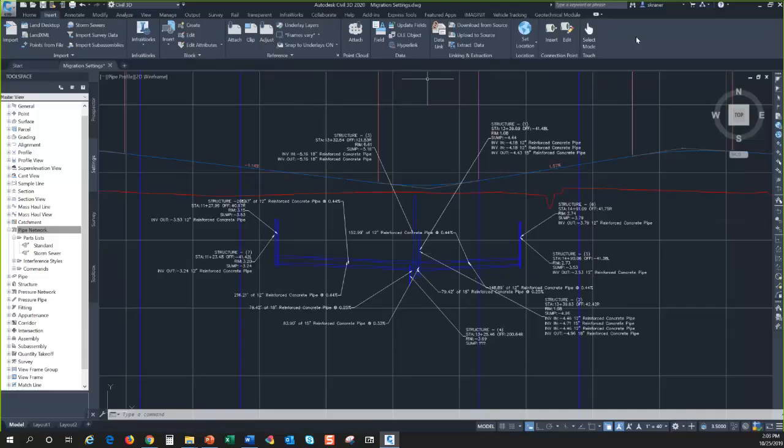One question that we had is, if we change any physical data, will it automatically update in Civil 3D? It updates the way I just showed it. So if you do change data, it depends on the data you change in your settings. But if what you're changing is pipe sizes and invert elevations and things like that, and your settings are set up right, just like you saw, it's going to change that.